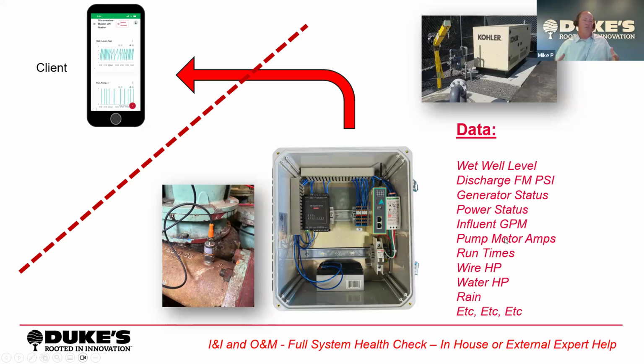So not only are we measuring if the pump is on and off and when it's on and off and how long does it run, but we're actually measuring the current values because they don't stay steady. And that's a key thing for, if you have in-house pump expertise, or if you have a local engineer that helps analyze pumps or design pump stations, like that's very key information to help troubleshoot and size pumps in the future and just understand what's going on.